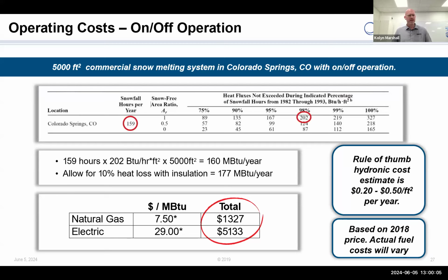Electric systems, it doesn't matter. The cable is the same temperature regardless of where it is in the mass. Point A is the same temperature as point B. So I can lay it in any direction, any shape. I can write my name with the cable. Doesn't matter. The only thing that I have to maintain is the wire spacing. So cable is pretty simple in that regard.